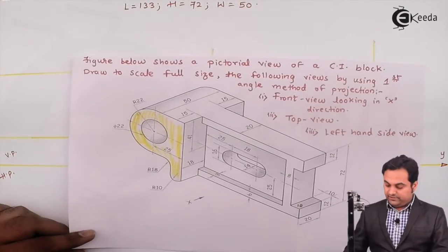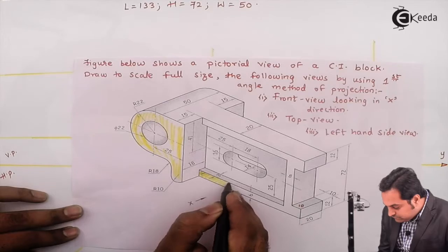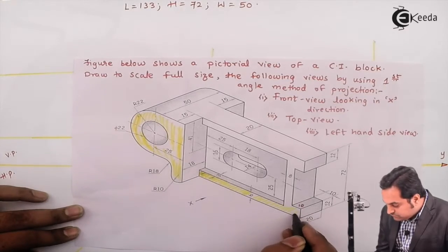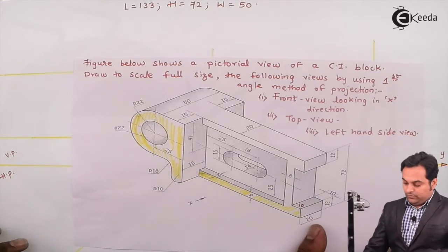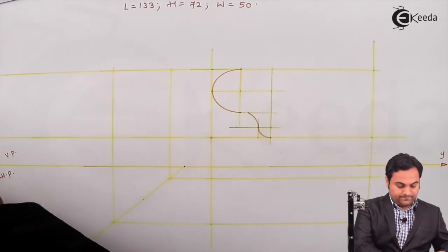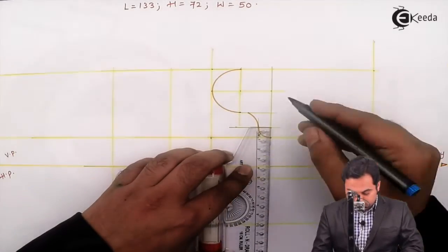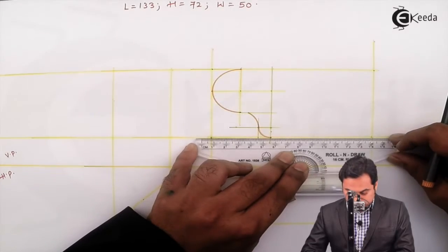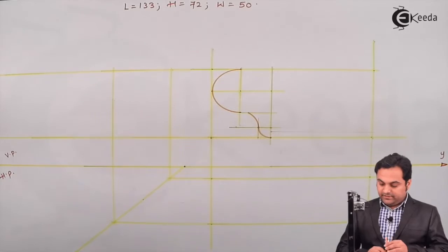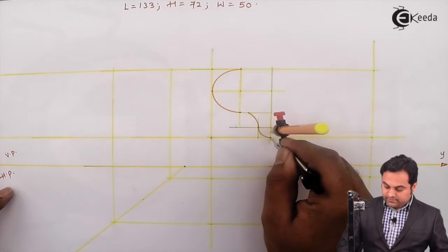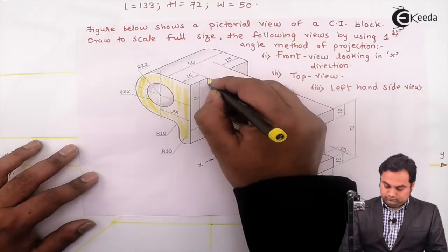Then looking from front, in that case, this rectangle will be visible. At first, it is having a height of 6 mm and then the height increases. So here, where this surface is ending, I'll measure 6 mm distance, measuring this. Similarly, taking that 6 mm distance from the other side, that is top as well, because another rectangular surface is there at the top.